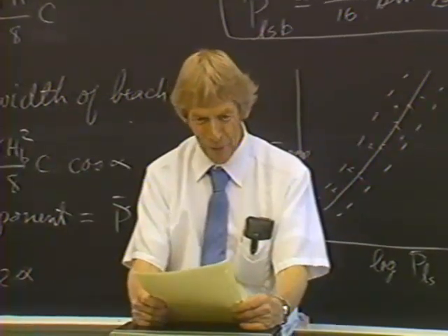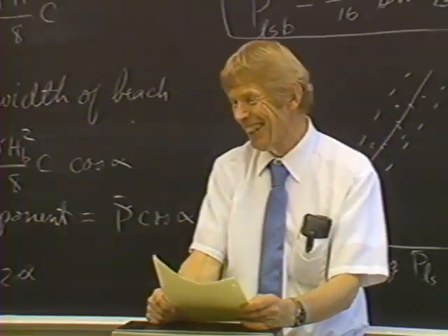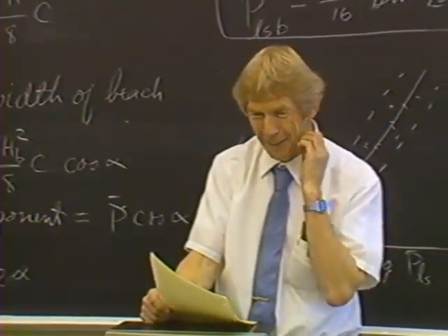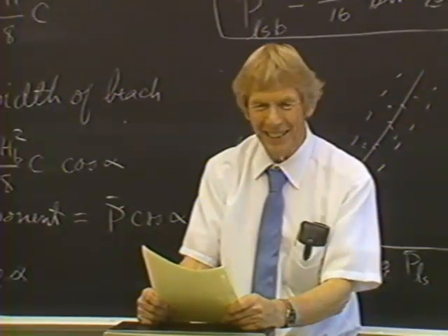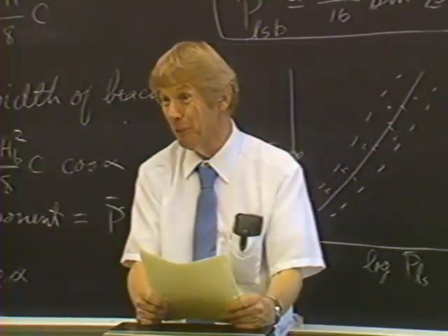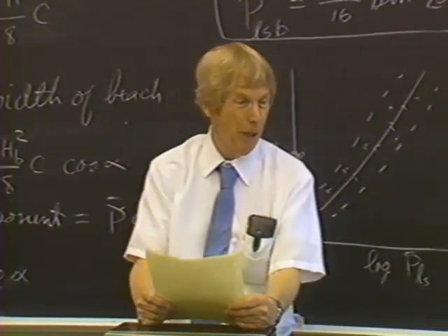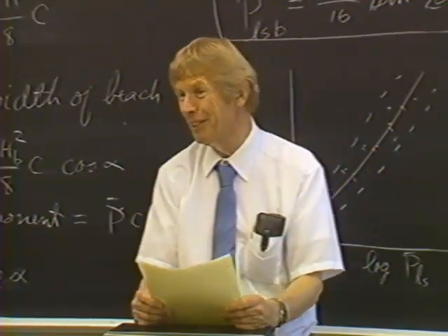Well, I really got into it with that one. The people that designed the plan said, "Oh no, those rocks aren't going to move, they're too big." Then I went down and talked to Professor Inman, and I said, "Doug, those rocks must move." He says they move at about 10% the rate of fine sand, which is appreciable. Fine sand moves maybe a mile a year. Well, 10% of that is 500 feet.